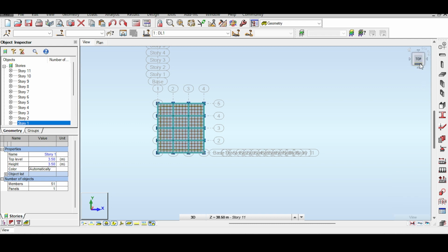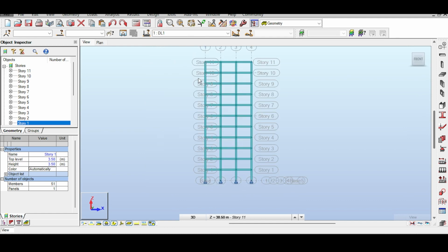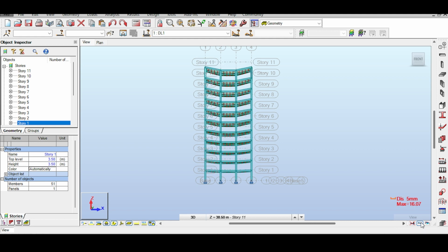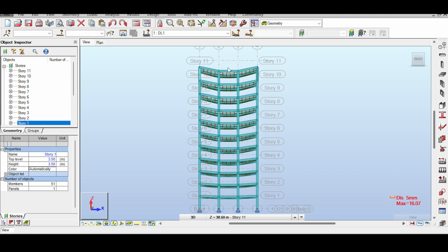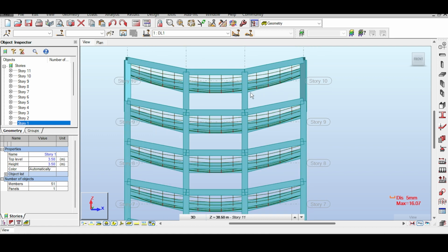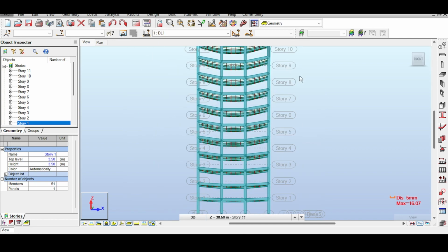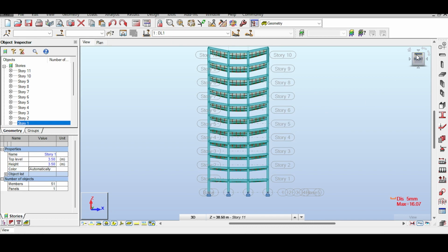If I go to the side or front and take a close look on a sideways motion left-right, if I open the deflection, you can only see a vertical movement. Don't be nervous because of those. The internal beams deflect more than the external beams, so that's perfectly fine. But you can see there is no sideways motion in the structure. That's from the front side.